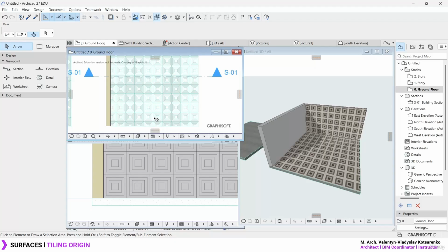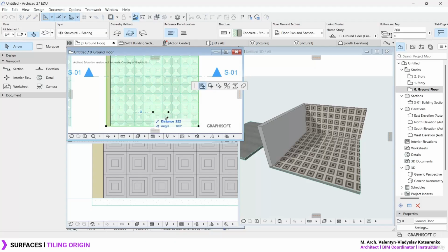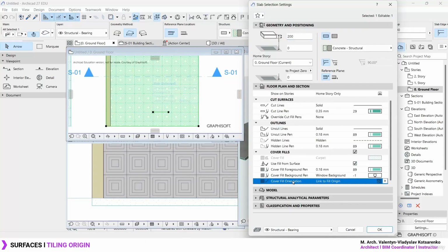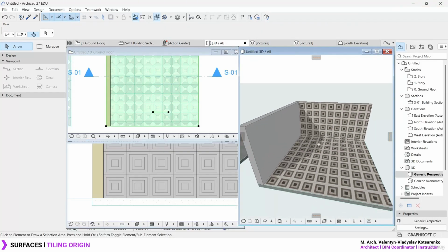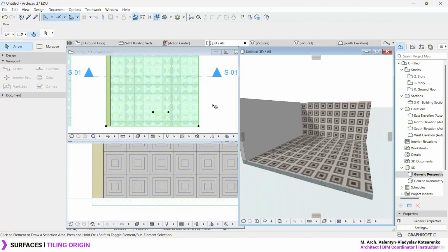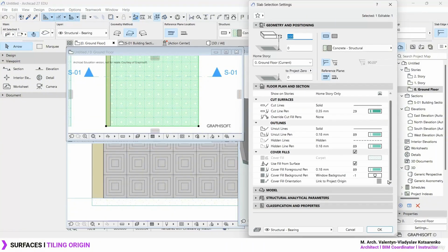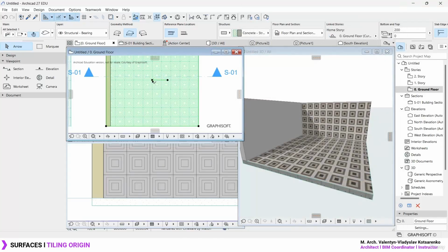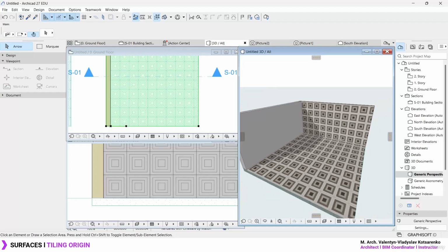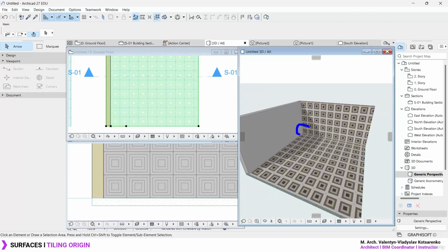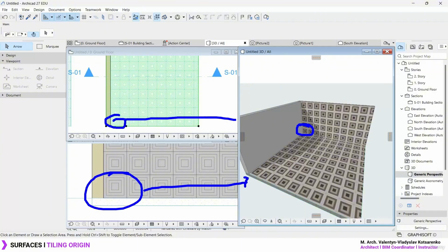Whichever change you make in 2D using the option to specify the cover fill orientation you get over here, just keep in mind that the 3D position will remain the same. But in my own perspective, I rather set it to maybe link to fill origin, press OK, and reset the position to these corners. So as always, take just a minute, 2 minutes, mess around with this option, check out how everything will connect in 2D and 3D, and once you have these options clear, we can move on to the next topic.